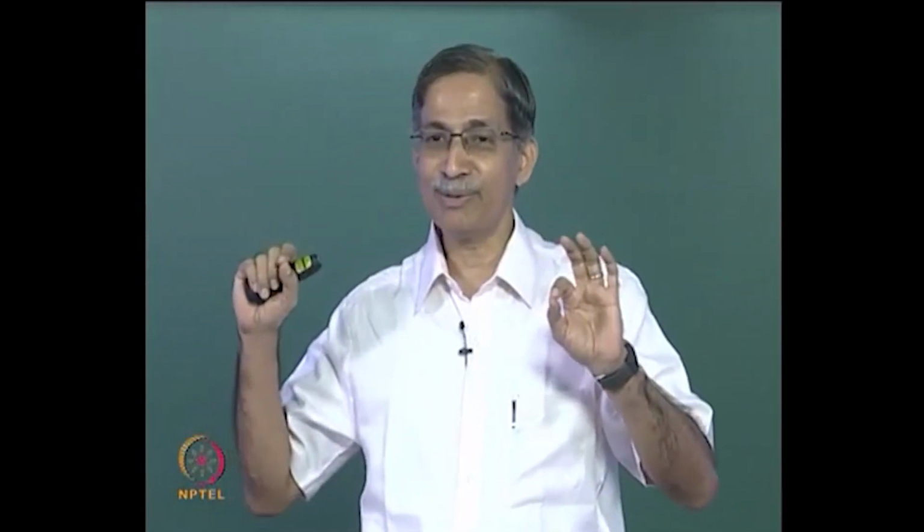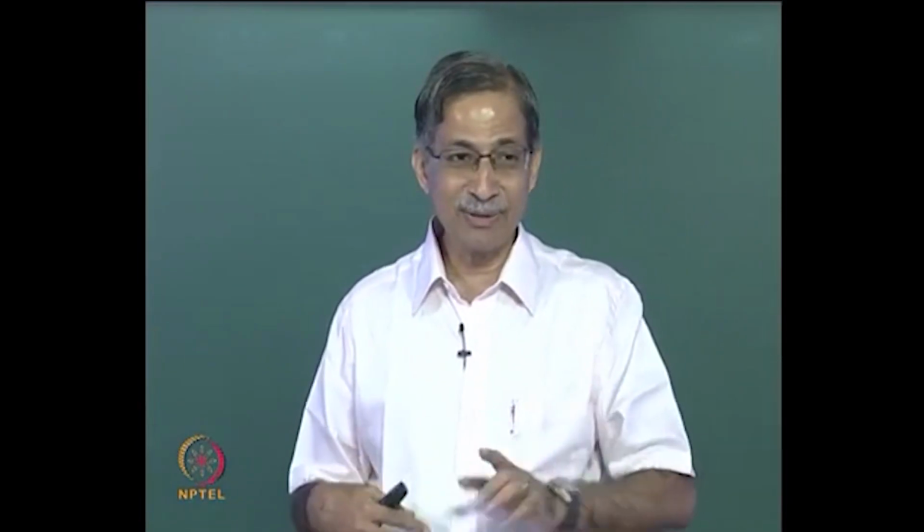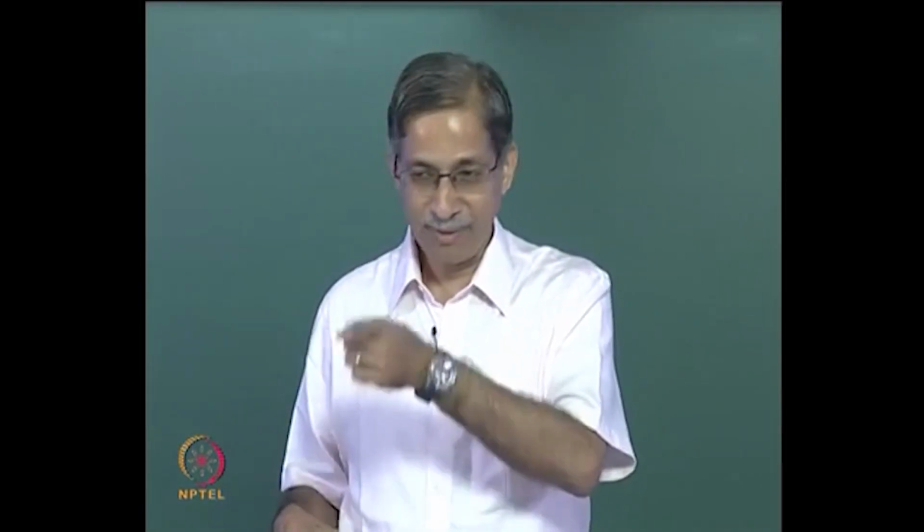Incidentally, at the end of the last class, one of you asked a question. Remember we tried to compare the flexibility method with the stiffness method, and the first point we wrote was what are the fundamental unknowns, and we said the fundamental unknown in the stiffness method is displacement, because the stiffness method is also called a displacement method. You have to first find displacements. You may be interested only in the internal forces, but you can't find the internal forces until you find the displacements. So your fundamental unknowns are displacements in the stiffness method.